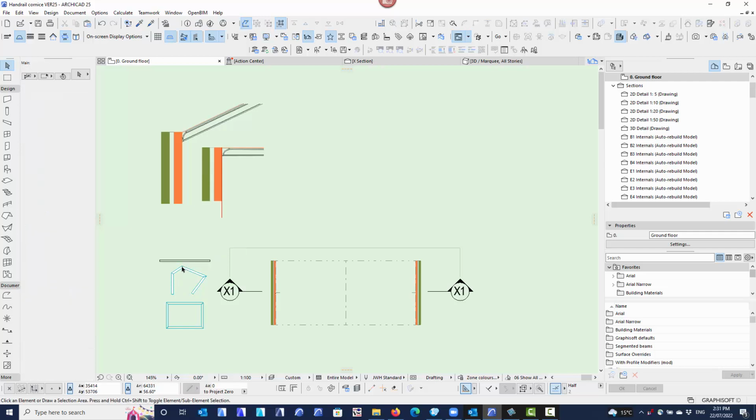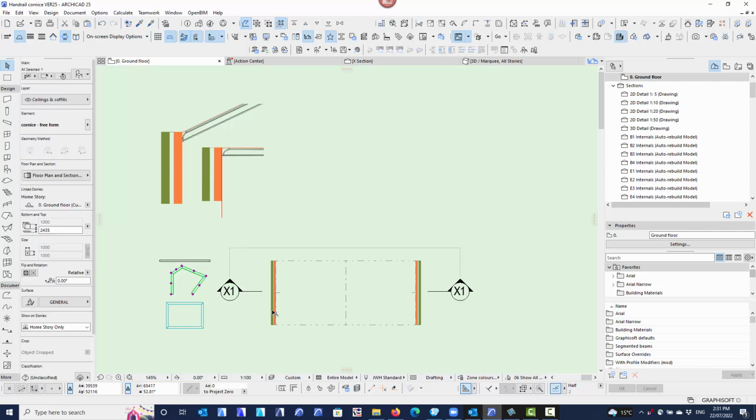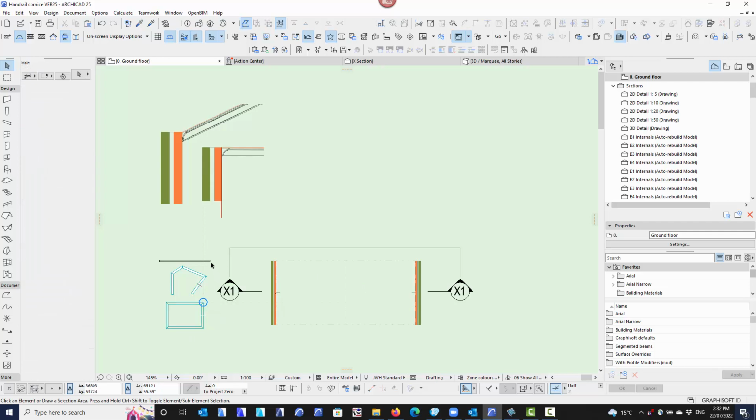The freeform cornice, although it will allow us to stretch it around the room, it doesn't allow us to rake anything. So we can't angle the cornice up the ceiling for the raking gable, and we can't roll any particular side of the cornice to match our raking ceiling. The auto cornice, because it's an accessory and it's a slab accessory, it doesn't work with raking ceilings because that raking ceiling is a roof, and therefore the accessory just will not associate to the roof, so we can't use it. So we're stuck with our raking cornice.